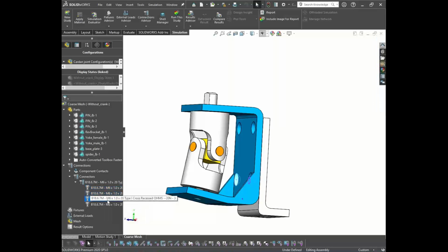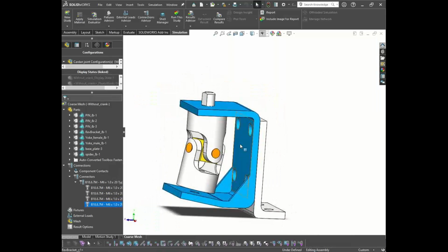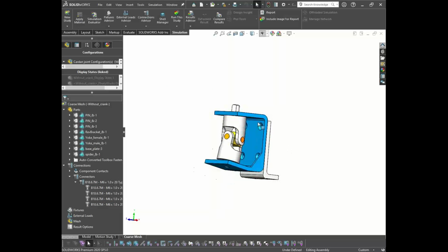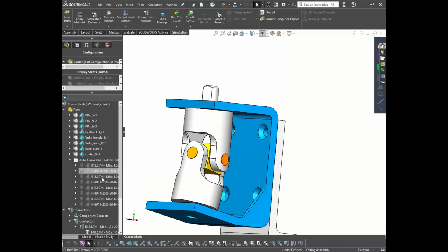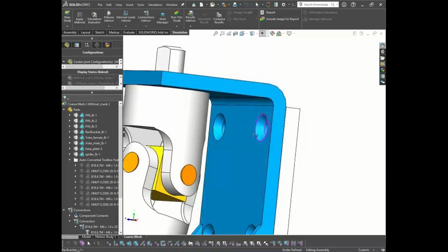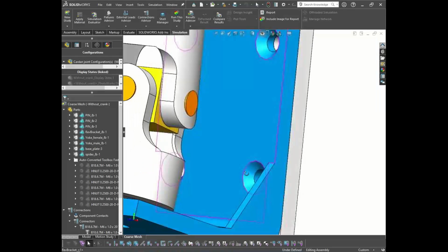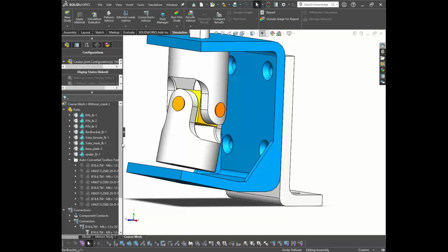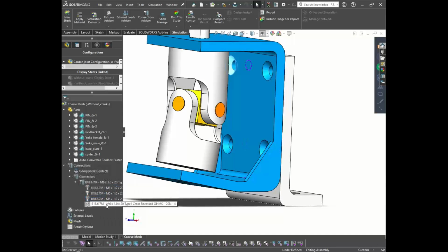So now it has created the bolt connector, that is, the data of the connectors which is joining these two plates has been considered now. So you need not model this. As you can see here, the bolt and nut are not there. So the solving or the meshing required for these particular bodies, I need not mesh them now, because the solver has considered them in the background at its end, and it has created the connector on its own.